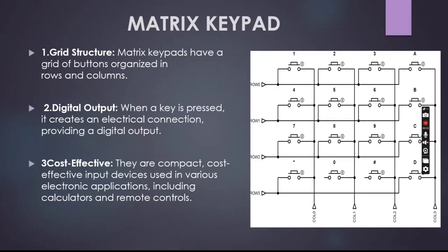In the keypad library, the propeller sets all the column lines to input and all the row lines to output. Then it picks a row and sets it high. After that, it checks all the column lines one at a time. If the column connection stays low, the button on that row has not been pressed. If it goes high, the microcontroller knows which row and which column. We have seen the schematic in the circuit section.